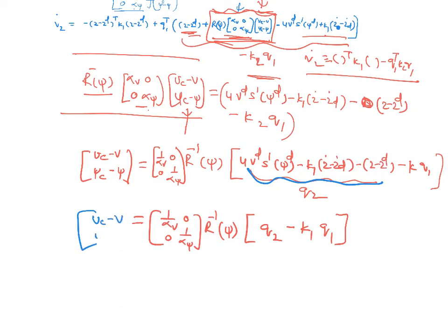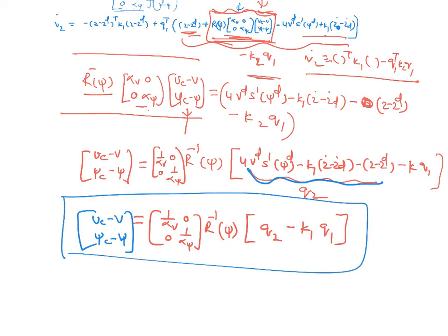If that was the case, then your game is over and you would have solved the problem. This is my control input using backstepping, or feedback linearization, whatever you want to call it. That's the controller that will achieve target tracking if you exactly know these parameters. The question is, this is not known. If it is not known, you'll have to estimate it, alpha v hat and alpha psi hat, use that, and we'll take it from here in the next class.